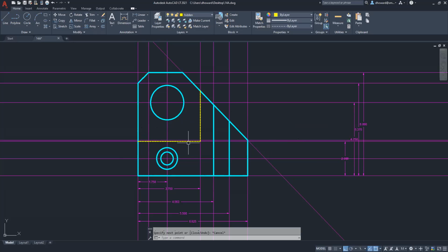The one thing I'm missing is the 5/8 corner, and it's showing that as 45 degrees. So again, that's a 5/8 offset on both sides. For fun, you could do a 5/8 fillet, and we could have done that up here as well. And I think I'm going to do that just for fun. You could offset these two construction lines 5/8 and then connect it if you wanted, or you could go to fillet command, F enter, and type the value.